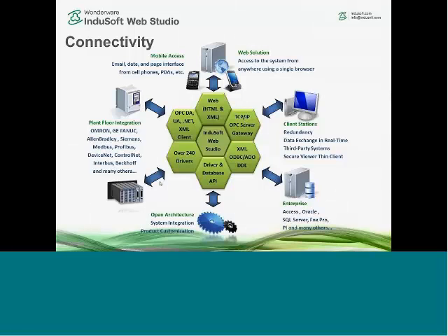I'm going to briefly talk about this and our connectivity and how it relates to packaging. If you take a look at most HMIs, the typical idea is we're going to communicate to a PLC and display that information. But we take that a little bit further. We have over 240, actually I think we're over 250 drivers now built into the product to communicate with not only PLCs, but things like temperature controllers, drives, and other devices, just about every protocol you can imagine.